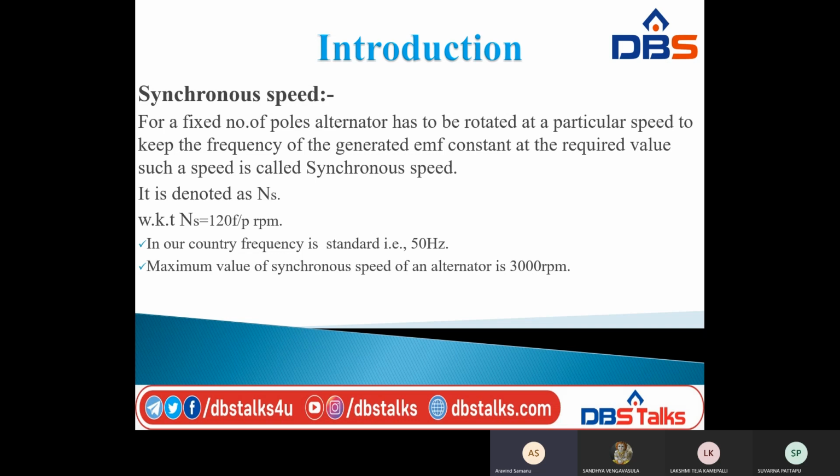For a fixed number of poles, the alternator has to be rotated at a particular speed. So we use a fixed number of poles for the alternator, and it has to be rotated at a particular speed to keep the frequency of the generated EMF constant at the required value.